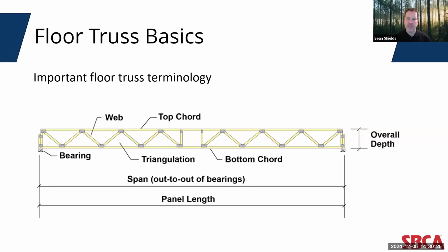Now, typically, floor trusses have webs arranged in a pattern to maximize triangulation of compression and tension forces, which is what allows the trusses to span large distances. There are also perpendicular webs used at bearing locations and at chase openings. Over bearing locations, these perpendicular webs allow for the transfer of forces between bearing walls above the truss and the bearing locations below. But as we'll note, because those forces aren't typically known by the truss designer, they're not necessarily designed to fully act as the single transference of load between the top wall and the bottom wall.